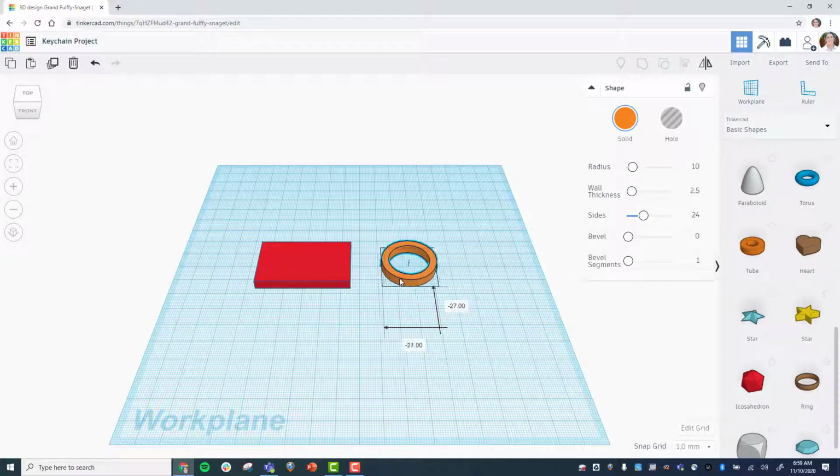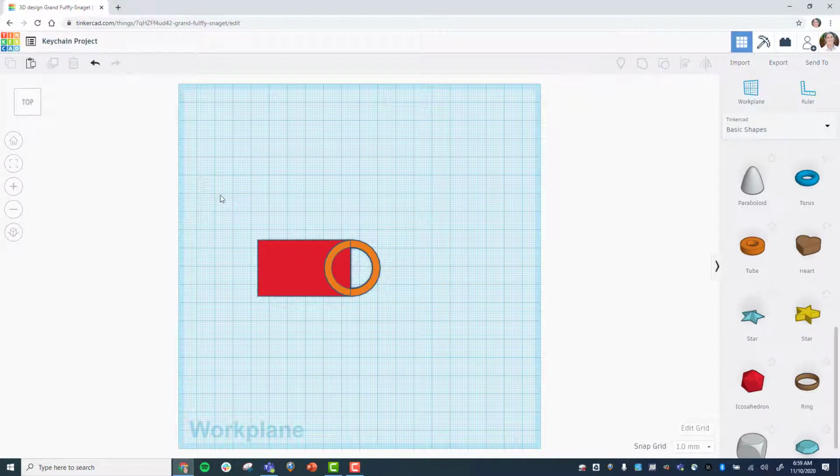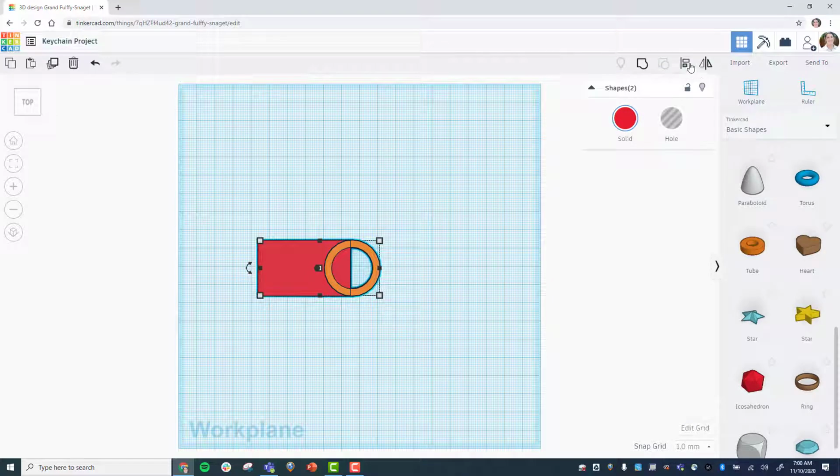You can left click and drag the handle and try to line it up as best that you can. But let's get the top view and see. To ensure that it is aligned, left click and drag a box around all the objects to select all, and you'll notice that the Align tool is now engaged. When you click on the Align tool, these handles will show up. As you select them, they turn red and you get a preview of where the objects will align to. We're going to align along the center midline, so click that option. And then left click to deselect.